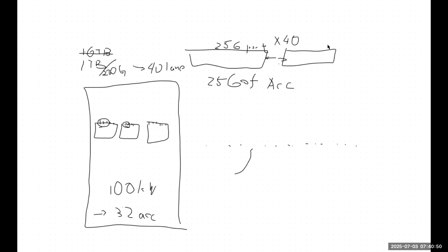It has to be optics, unless you don't want to connect something like 256. All you want to connect is 32, then you can do electrical. But if you want to connect more than 32 accelerators, or you're pushing to the extreme like NVIDIA 72, where the scale-up network connects 72, using everything liquid cooling and putting 500 kilowatts into a rack, you cannot; you have to go into optics.